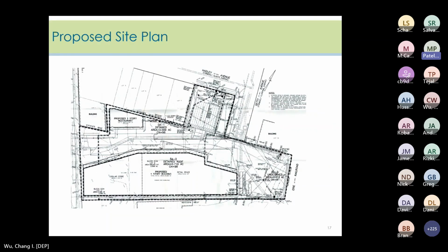But what ended up getting developed was different than what was approved. Eventually, they added a proposed 1-story, and they lost a pretty big area that they were considering pervious around the island, and they ended up putting an underground infiltration system. Under the current rules, using a subsurface infiltration basin for a drainage area that's less than 2.5 acres can be considered a small-scale GIBMP as long as the design criteria are met.